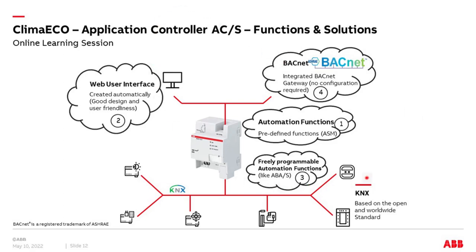All these 4 functions can work in parallel. They are independent of each other, but it's not that you have to select 1 or 2 and then the device is occupied. You can use everything in parallel, but of course it's also possible to say I don't need all these things, and only the BACnet interface would also be an option here. Of course, if you need only freely programmable logic, you can use directly the logic controller ABAS. So it's up to you, up to your project, what kind of functions you use here.